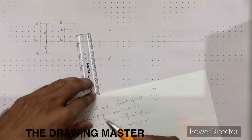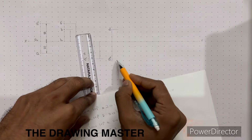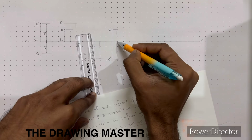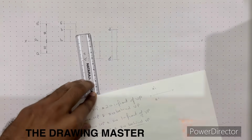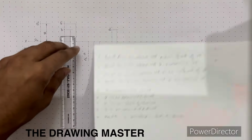And then you can write the dimension. Here you can take the extension line and dimension line. The extension line should not touch the object and the dimension line should be at a gap of 8 to 10 mm. This space should be there. Okay, let's go for the next problem.